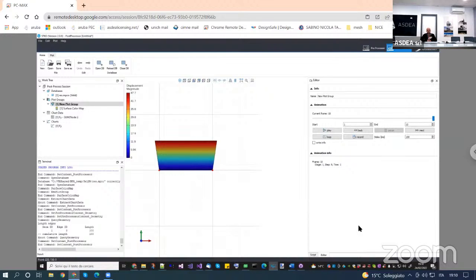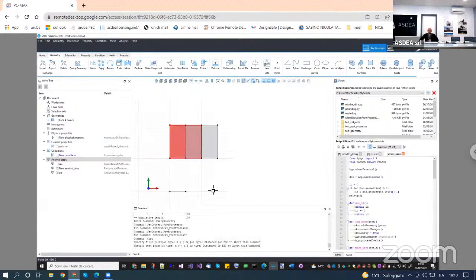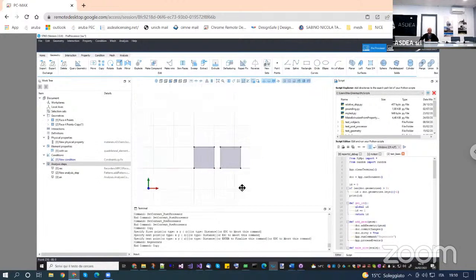Instead, if you do dynamic analysis, either linear or non-linear, if you apply the entire load in a short time, okay, it will start bouncing. Okay, so you will need to apply the load in a distributed fashion. Okay, so to do this, what you need to do is not to follow this approach. Now let me copy this output here just to make sure that we obtain the same results but with a